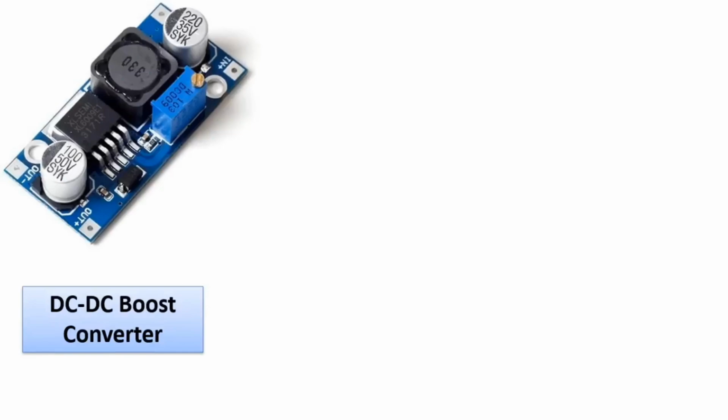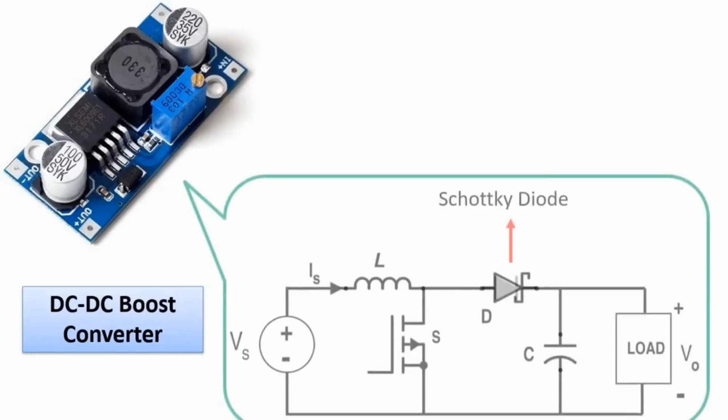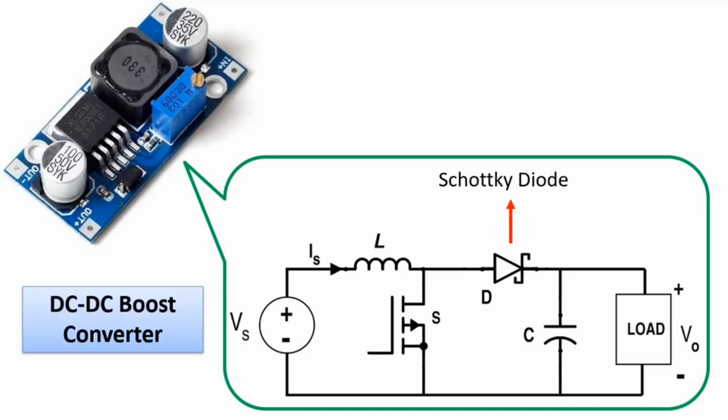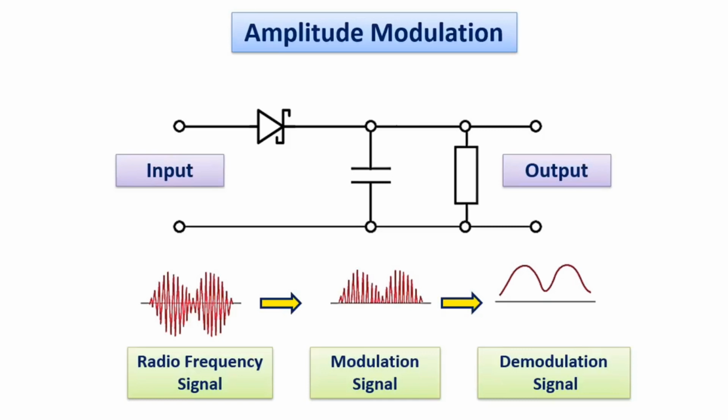Here you see a DC to DC boost converter. The circuit diagram is basically like this. The boost process is based on the switching speed of the MOSFET in the circuit. In this circuit, triggers are made at high frequency values at the kilohertz level. Therefore, instead of using normal silicon diodes, Schottky diodes are preferred to respond to high-frequency switching speeds in order to obtain healthier results.